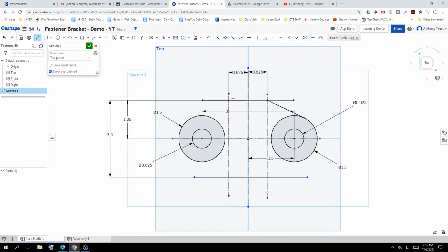I'm going to press L. I'm going to do the other three. It's the same operation. And sometimes you may not get it, so you have to move that point up and down. There's a large snap to this. So as long as you see that 1.329 and the tangency symbol, you know you got it. So press escape, do it again, start at the intersection, find yourself a tangent point that says 1.329.